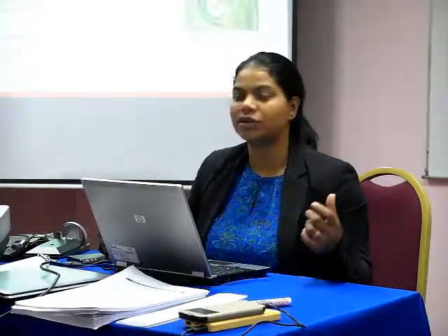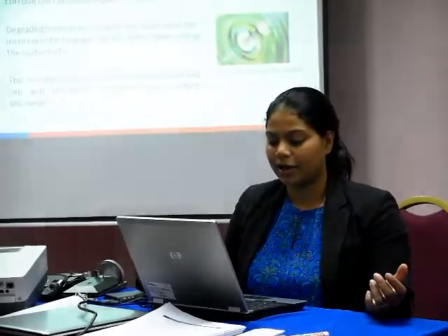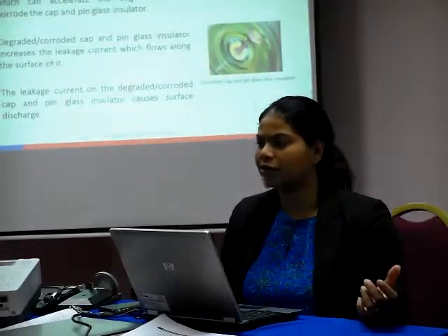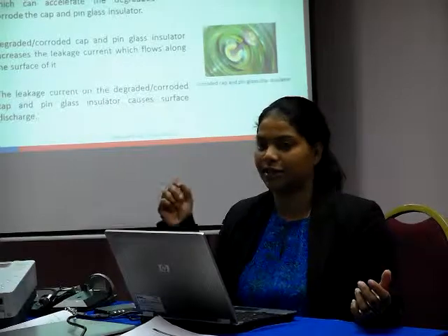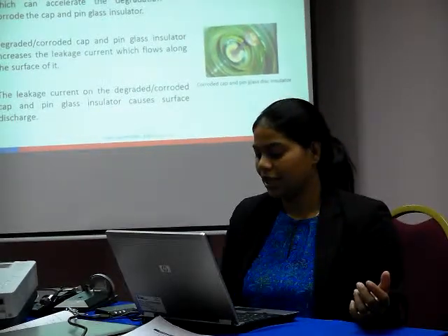So when it's corroded, the leakage current along the surface of this pin insulator will increase. So when this leakage current increases, it will cause a surface discharge. Okay, so